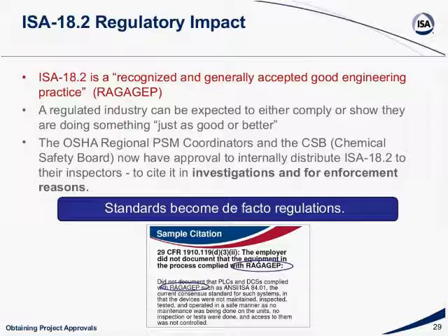And so it's no longer a case of there's no teeth behind the program. Now there is, and now you can be cited, and depending upon how grievous the event was, the citations and the enforcement actions can be very, very significant. And so RAGAGEP changes everything because now it truly is a standard recognized by the agencies that can come in and determine whether or not you've met the requirements of alarm management.